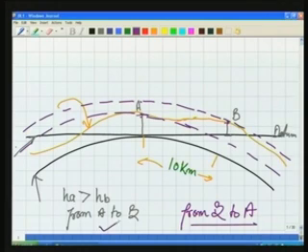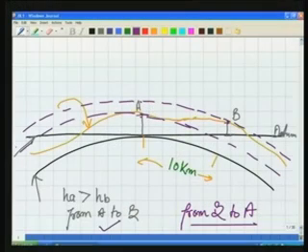What is the case here? So, what do we mean by this? We mean that if we are taking the horizontal plane for measuring elevations, our elevations will be wrong. It might happen that we give the elevation to a point, as here in this case A, more than to a point B, despite the water flowing from B to A. So, we must always measure the elevations from the geoid, not from the horizontal plane.